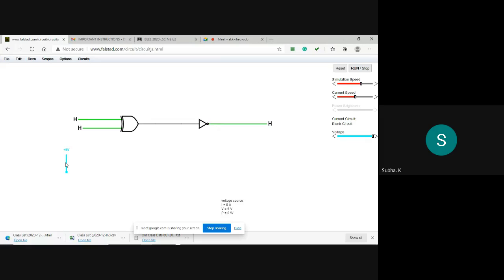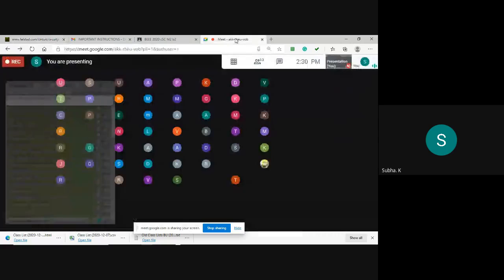Okay. So you can fix the values here. You can change it maximum to any value that you want. So there is a slider there. Just by varying the slider, you will be able to vary the voltage. This variable voltage you can use if you want to obtain the BJT characteristics, Zener characteristics. That way it will be easy rather than keeping a fixed voltage source and every time inputting a data. Okay, understood this component? Yes, ma'am. Any other thing that you want to know?